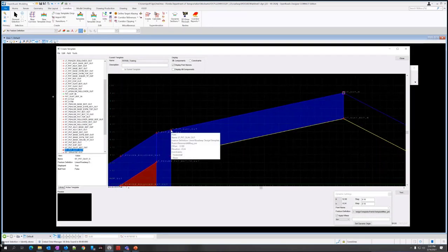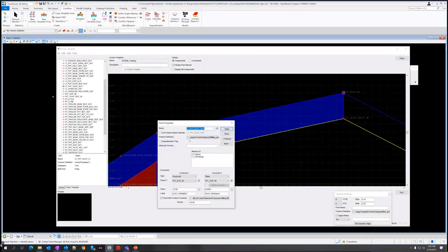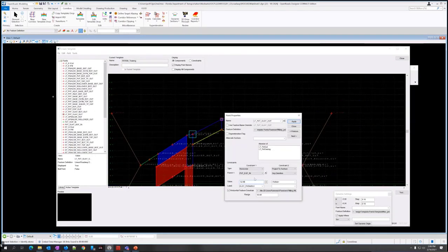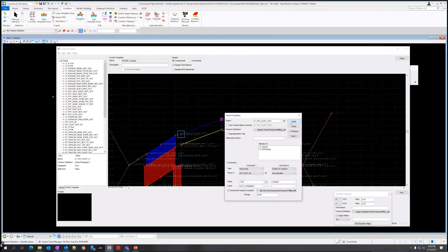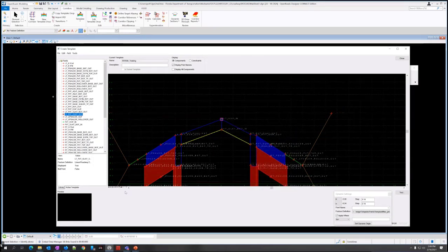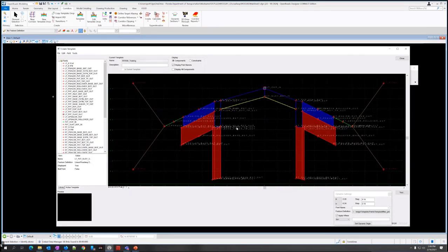And we're going to do the same thing for the left pavement overlay out point over here on the left side. Double clicking on that. Okay, so I'm checking the horizontal value. Projected surface looks good. Horizontal value needs to be -7. I'm going to change that and click apply. You see it move over here. So I can close it. Looks good. I'm going to fit to view. You see the whole thing. I'm going to come over here and do file save. Don't lose any of my changes.